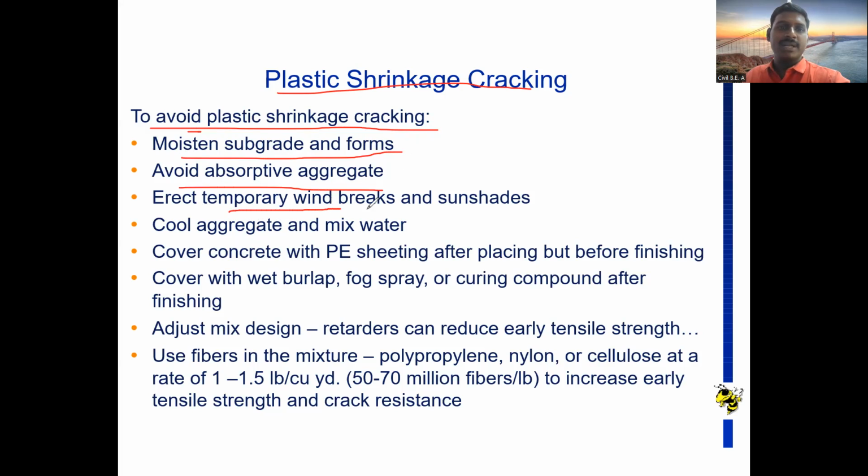Then erect temporary wind breaks and sunshades. Then cool the aggregate and mix water. Why do we have to cool the aggregate? Because, as I told, aggregates absorb the water which is present in the concrete. Whatever water we are adding into the concrete, that water is absorbed by the aggregates.